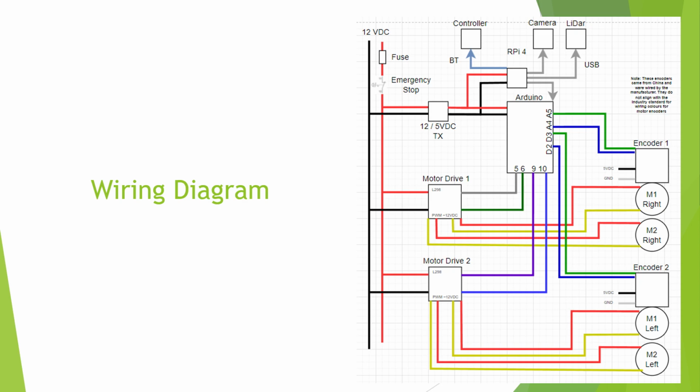And the whole mower can steer. If we drive the right motor forwards and the left motor back, we can turn left. If we do the opposite, we turn right. That's what a skid steer effectively is, or some people call it diff drive. That differential in rotation directions gives us steering. If they both drive forwards, we're going forwards. If they both drive back, we're going back. And if we change one or the other, we're turning. That's skid steer.